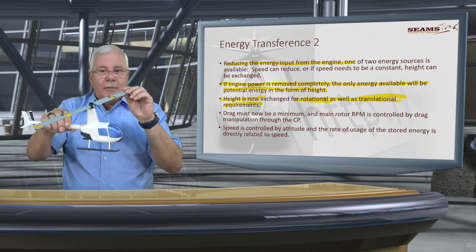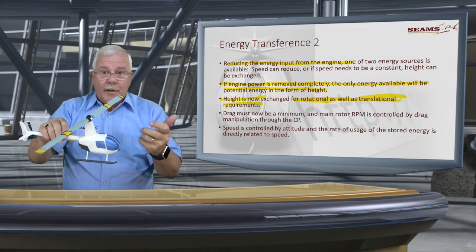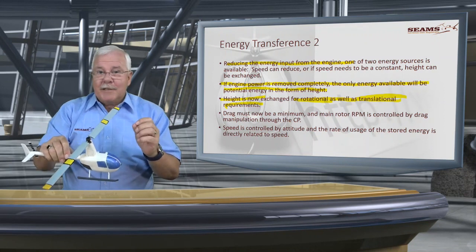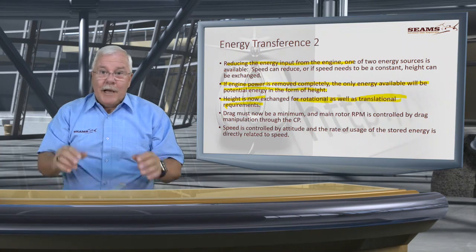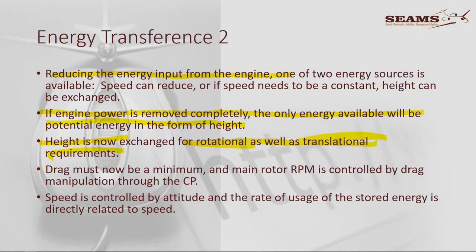And the only way that we can manipulate is just by increasing slightly more the drag, by putting a little bit more collective pitch. Well, that's good, because at the end of the day, the rate of descent must be stabilized as well, because sometimes this whole effort will have to stop before we get to the ground. And only energy and the usage of energy will sort that out.